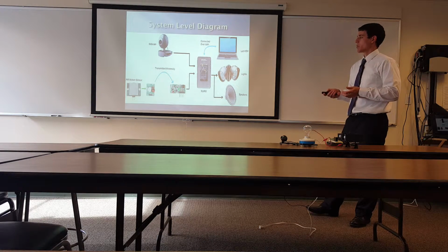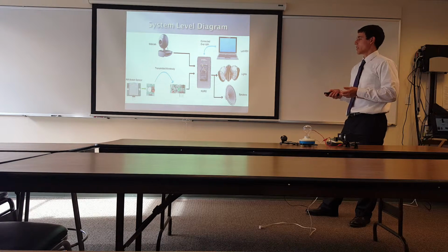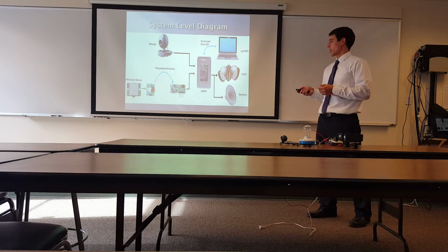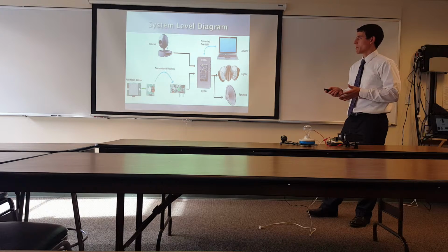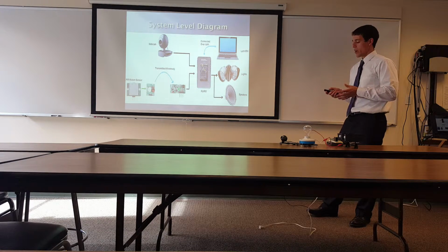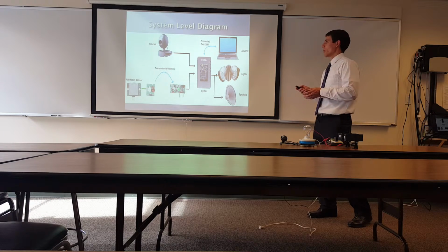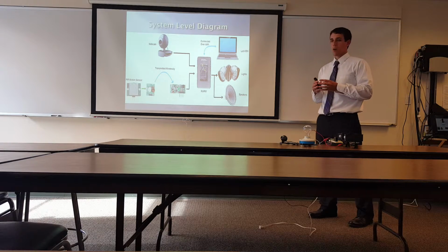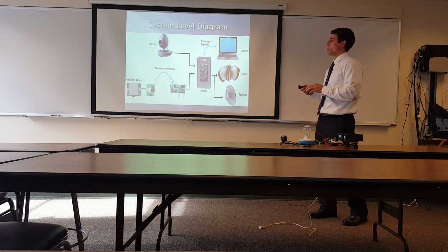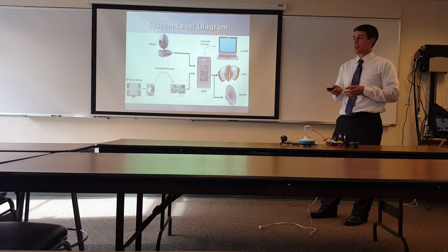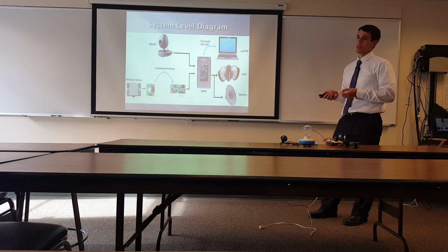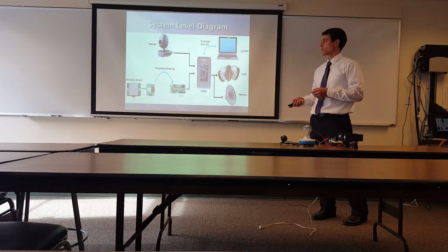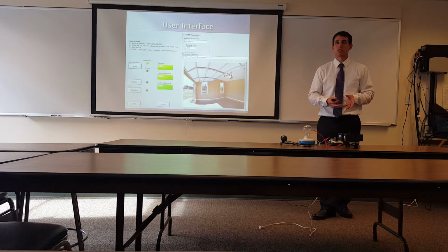So I have the PIR motion sensor transmitting its status into the RF transmitter, which then sends its data to the RF receiver, which transmits its data into the myRIO. While this is happening, the webcam is always sending data into the myRIO. The myRIO collects that data and sends it over the Wi-Fi to the computer, which has a LabVIEW program running. The LabVIEW program will then acquire the data, manipulate the data, and send data back to the myRIO. Based off that data, the myRIO will either turn on the lights or the speakers based off the user preferences. So how will the user interact with the system?